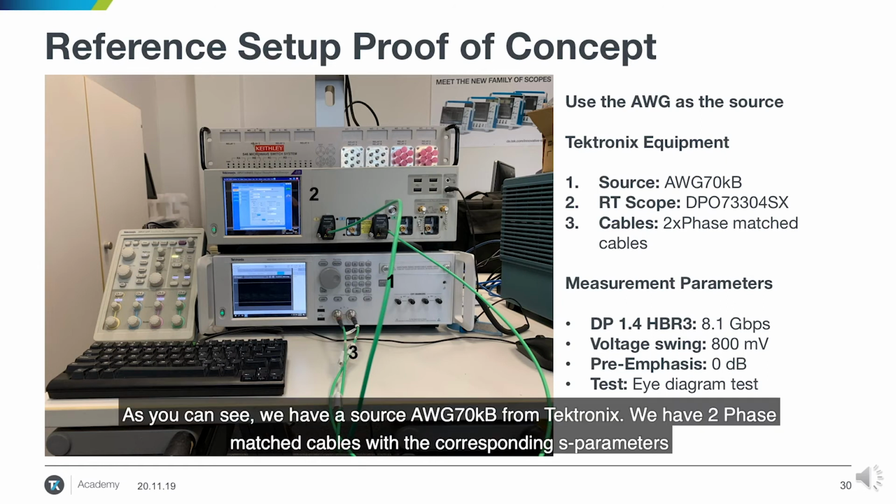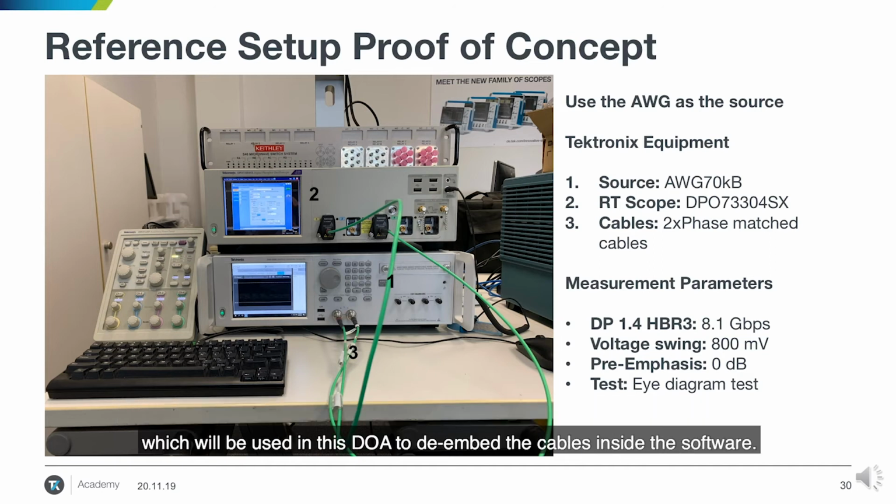As you can see, we have a source, AWG70K series B from Tektronix. We have two phase matched cables with the corresponding S parameters, which will be used in the SDLA to embed the cables inside the software.